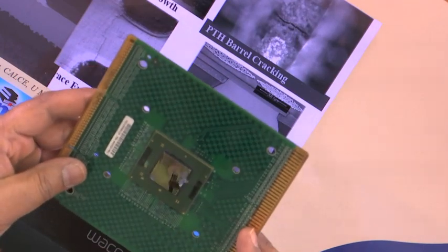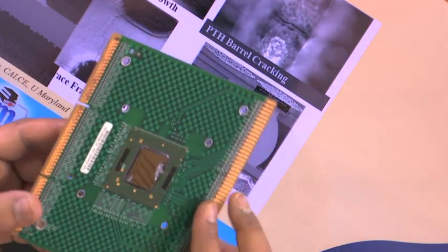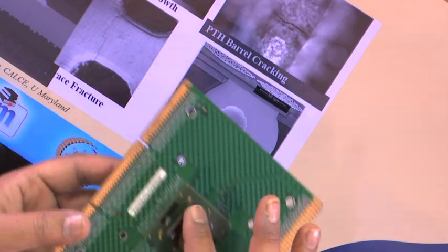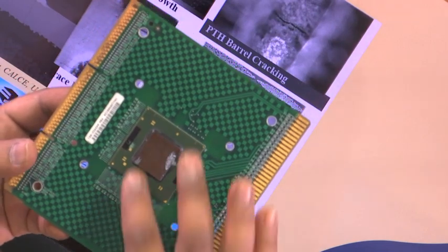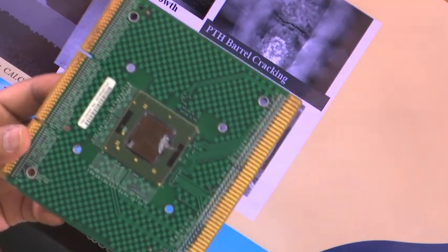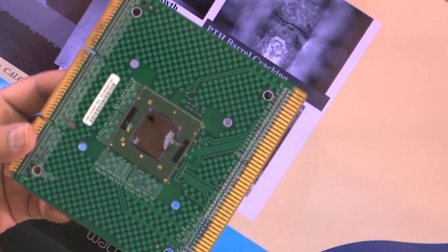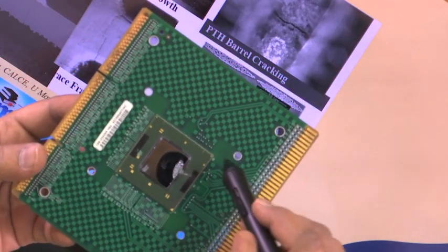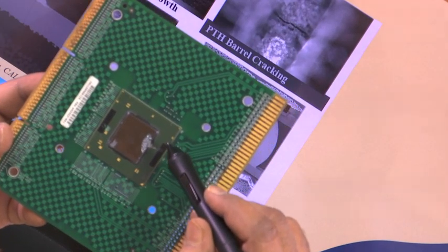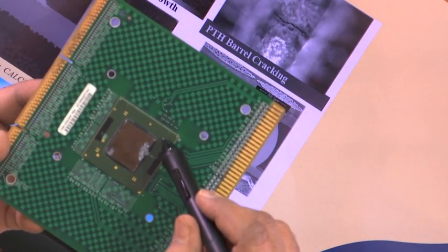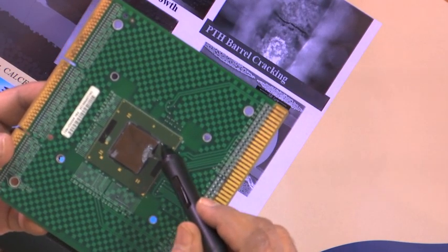Now, since I am showing this, let me also show you something very interesting. Say this is a ball grid array on an organic substrate or a package and on an FR4 motherboard. So, both are organic, the substrate is organic material, the motherboard is also an organic material, similar CTE. Now, this is a ball grid array attached, BGA attached between the motherboard and the package as well as between the silicon and the substrate.